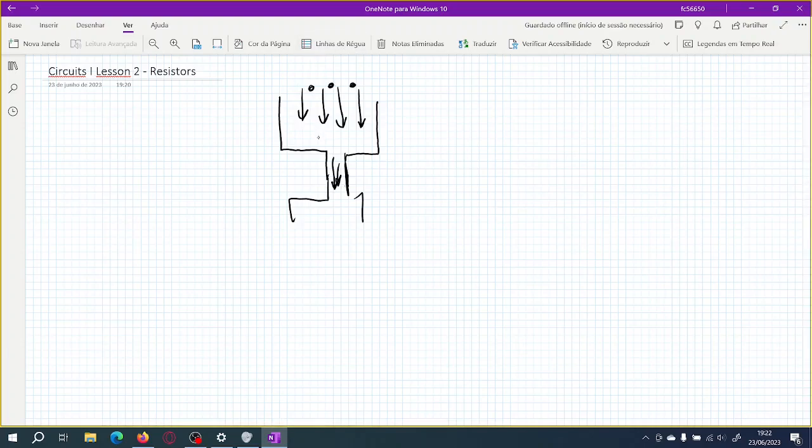So for example, if you have a pipe that narrows at a certain point, and you have a flow through it, if it is a steady flow, you can say that the flow over here will be the same over here, right? But because of that, the pressure on this side will be higher than in this part, causing the flow to go in this direction, right?